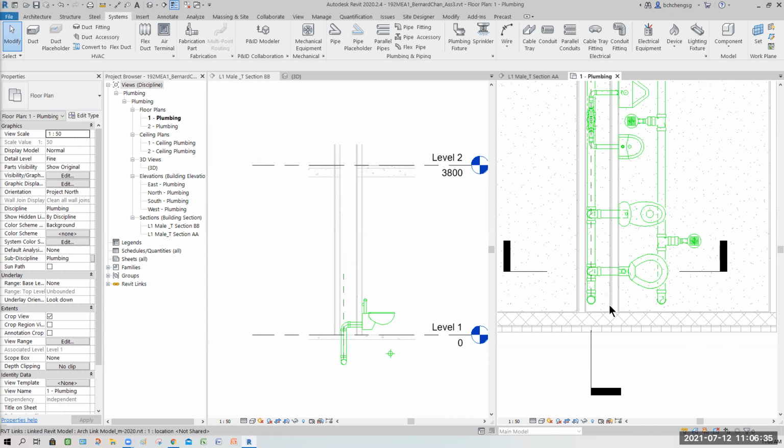So from here, I want to see how I'm going to draw my water pipe. Meantime, the main pipe outside normally, if not wrong, is around 50 mm, because the pipe cannot be too big; too big, pressure will drop. So I think the largest is 50.